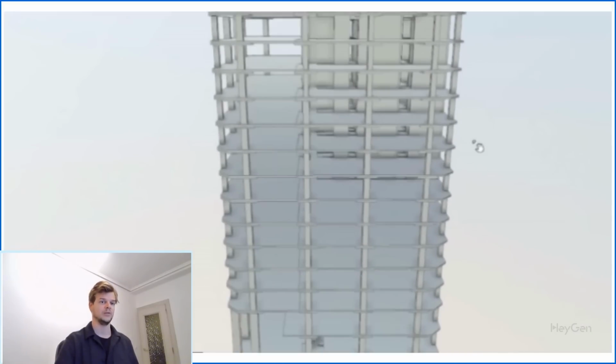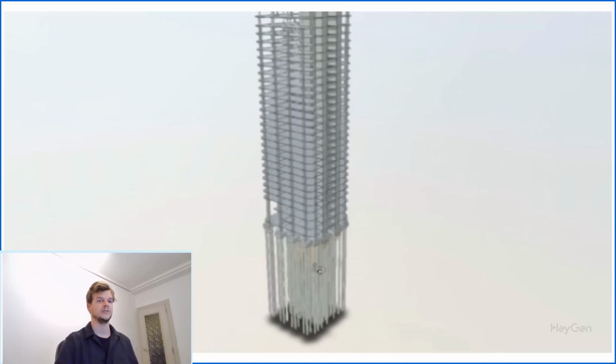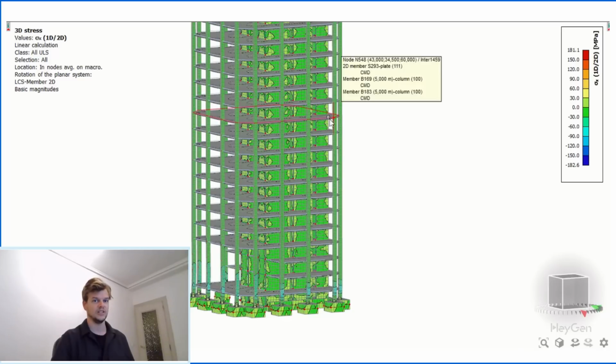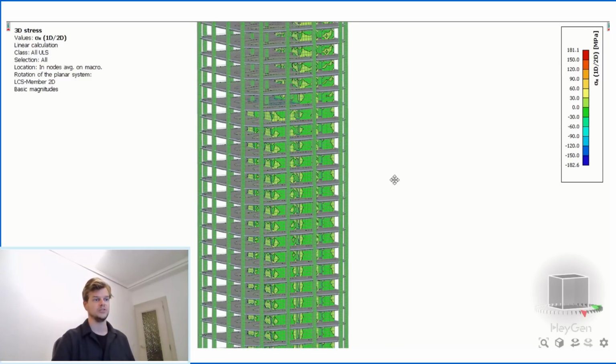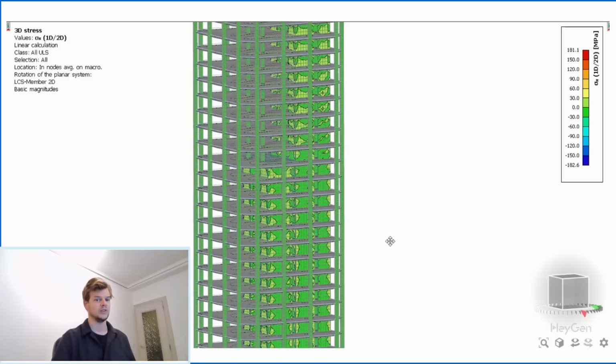The total estimated weight of the construction without piles is around 50 million kilos, resulting in significant vertical and lateral demands on the structure. Here we see the full skyscraper model loaded and calculated with estimated earthquake loads in the FEM software. At the base, you can clearly see the concentration of stress around the pile caps and lower columns.